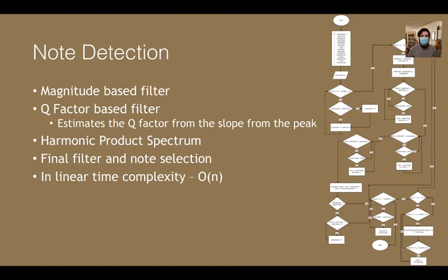And then we have the final threshold, which does scale based on RMS, as I mentioned earlier with the block diagram. Most importantly, this entire algorithm was designed to avoid needless divisions or right shifts and completely avoid any floating point operations. Even if it did, it would still be in linear time, but since our microcontroller doesn't work well with those operations, we used a lot of left and right shifts and made the note detection very, very optimized to reduce latency.